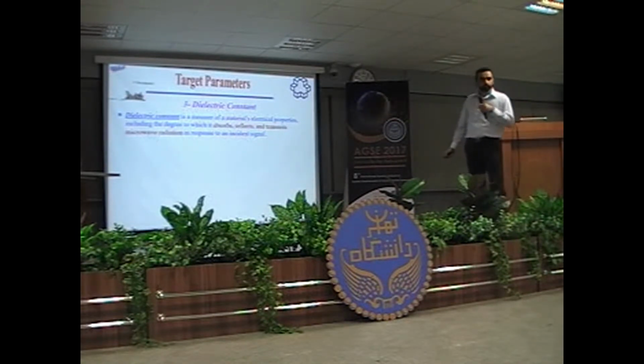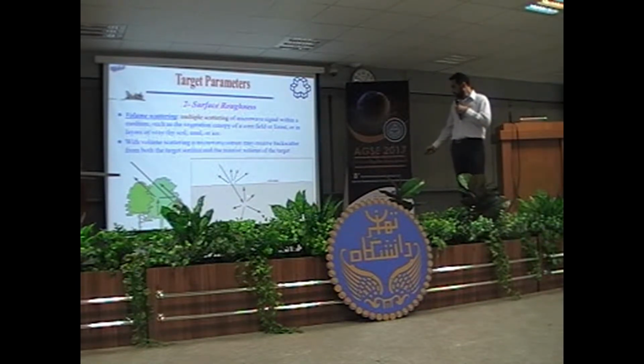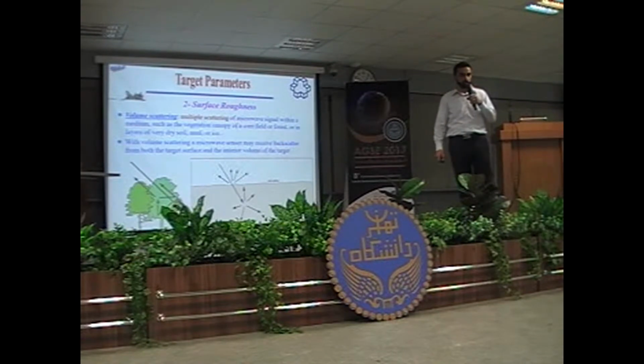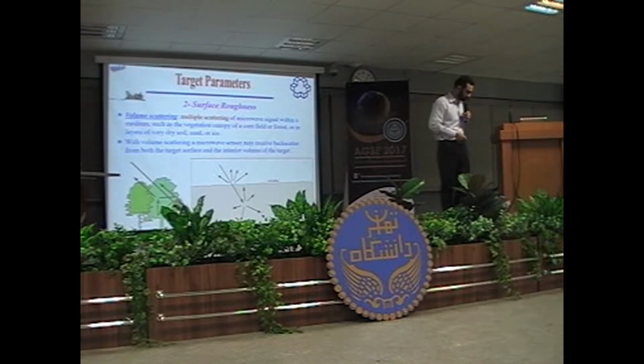Excuse me. Two slides before, you showed the subsoil surface. Can you explain that penetration level, how much it can... Yeah, that's a good question. Actually, even in the soil we could have penetration, but the amount of penetration depends on two things. First, the wavelength of the radar. If the wavelength is larger, the amount of penetration will be higher. And the second is the dryness of the soil. If the soil is completely dry, I will show you later about this, then we will have a large amount of penetration through the soil. But if it is wet, then the amount of penetration will be very small. I will explain about this in the dielectric constant part.